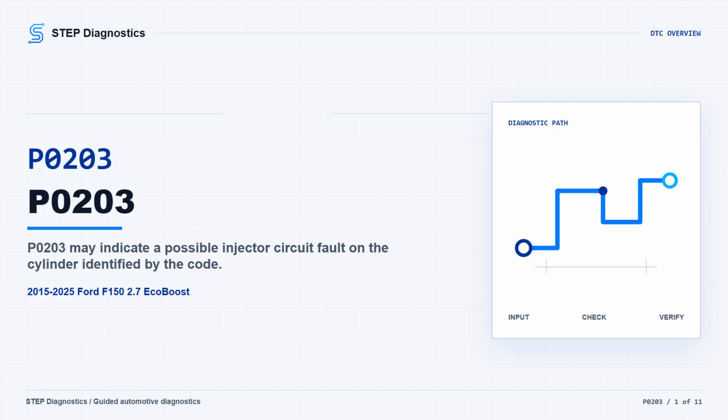Broadly, this can involve the injector circuit, wiring, terminals, connector fit, power or ground integrity, scan tool command and response, or a possible control side issue. Treat it as an electrical diagnosis first, not a parts call.